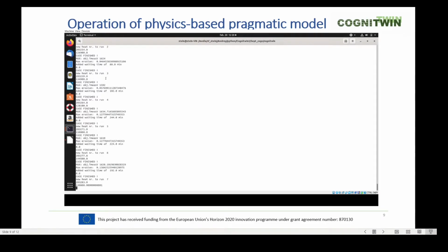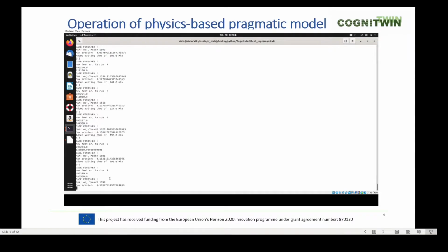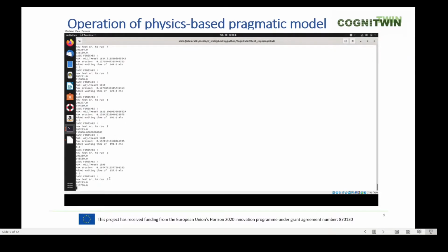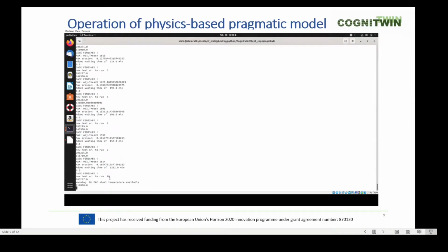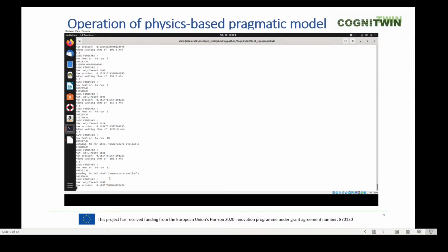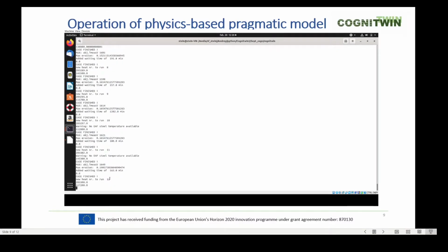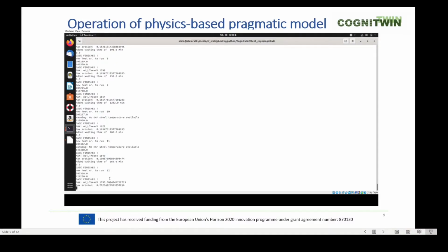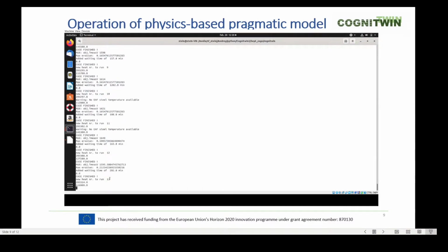And we can see now that already the code has been running, say, eight uses of that ladle, starting at the beginning of 2019. And there's quite a big number of uses during 1 year. So typically one use will take like 4 hours from when metal was filled into it from the electric arc furnace until the ladle will come back for another use.